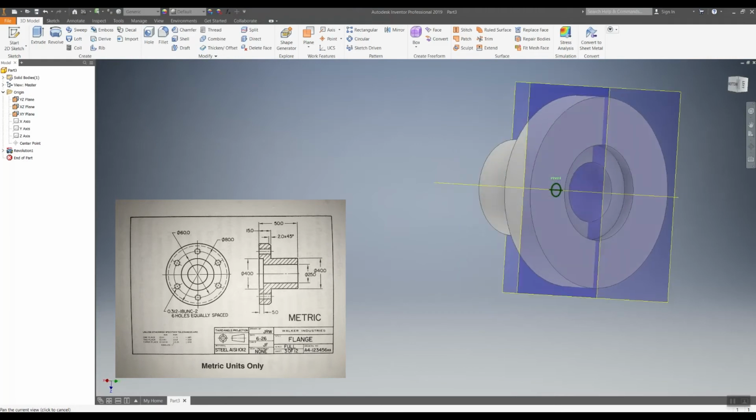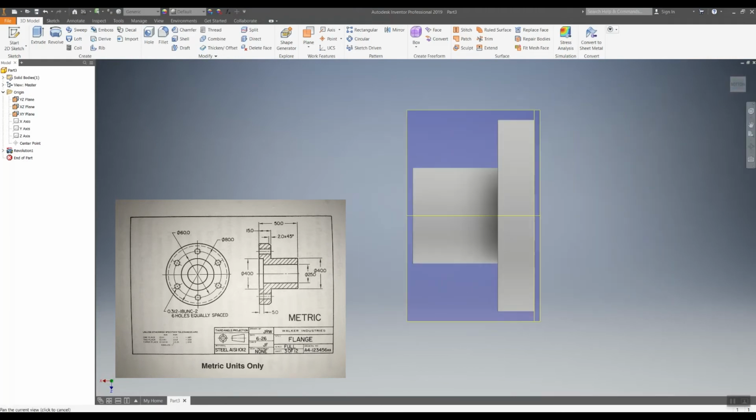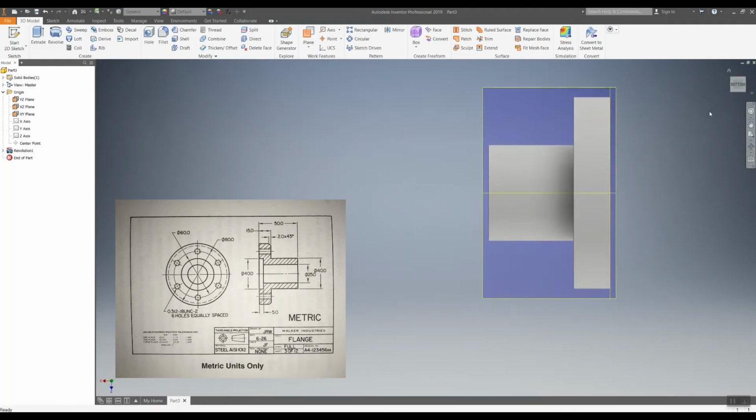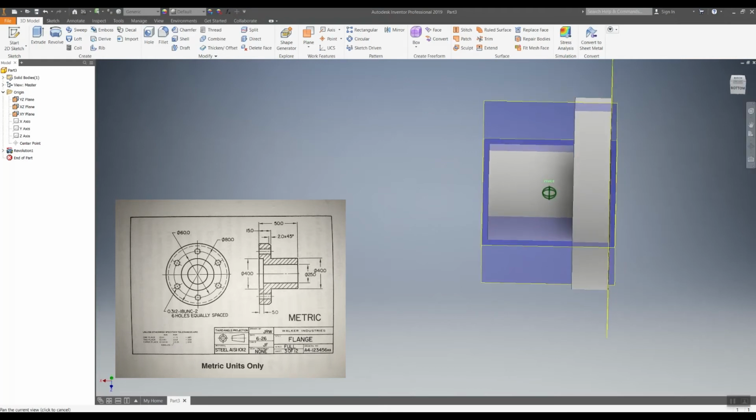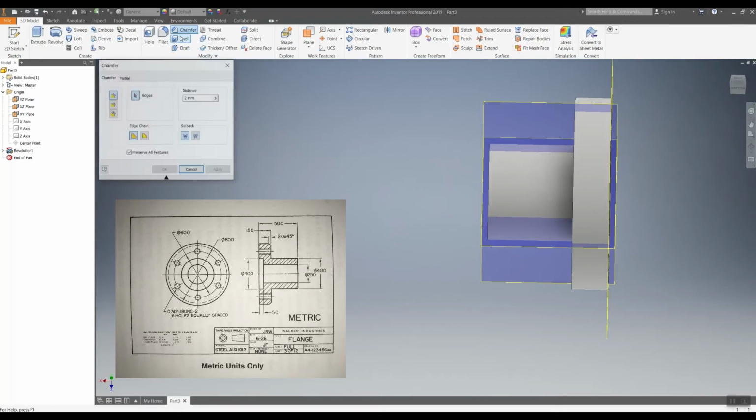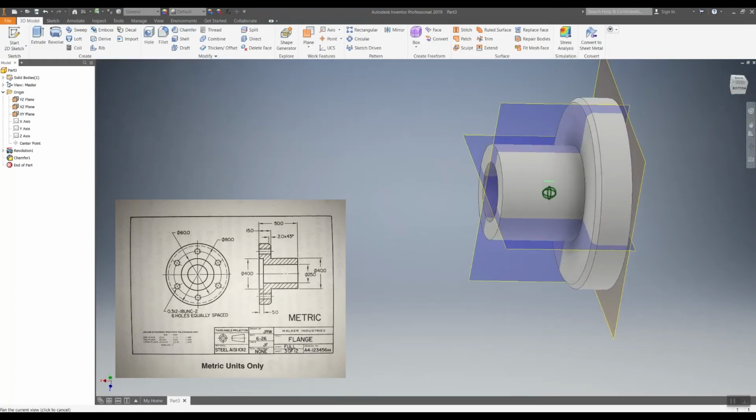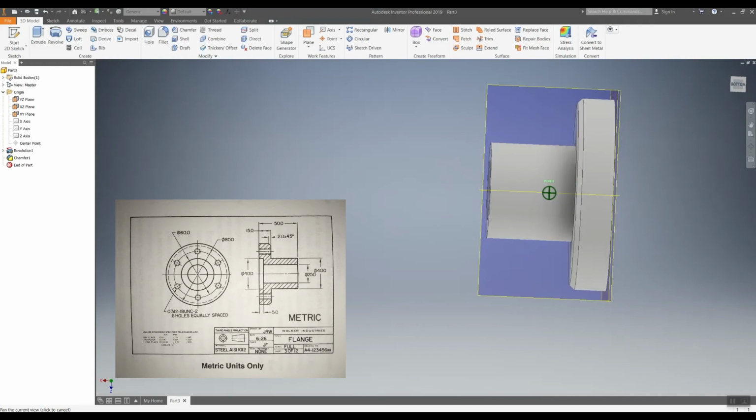And this is what the entire thing looks like. Here is my side view there. I still have to put this chamfer on this back side here. Let's do that real quick. If you see, it is 20 at a 45. We hit chamfer. If we just simply do 20, it's going to cut that over. We click that edge, hit apply, and our chamfer is in.